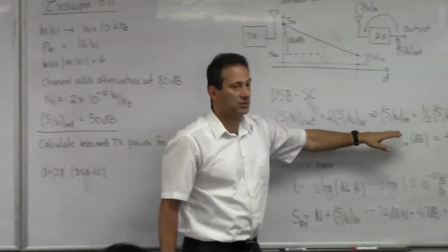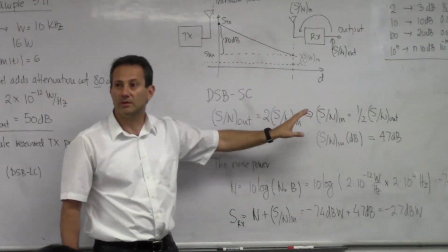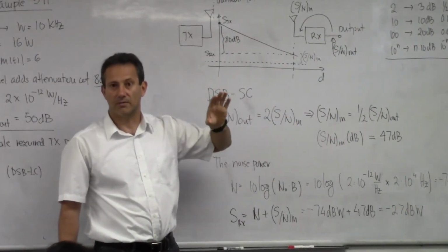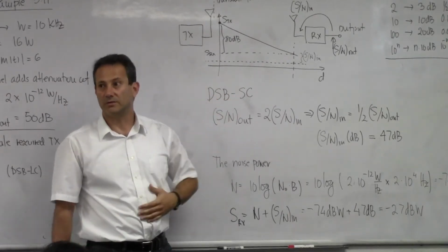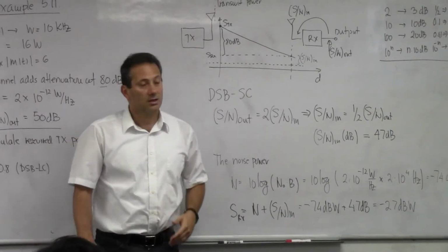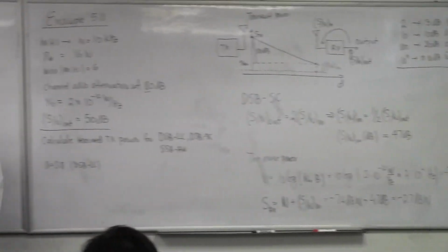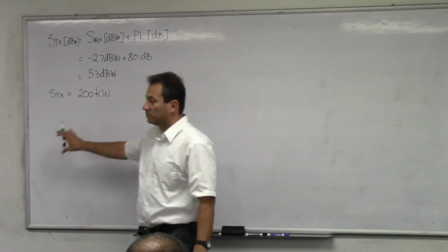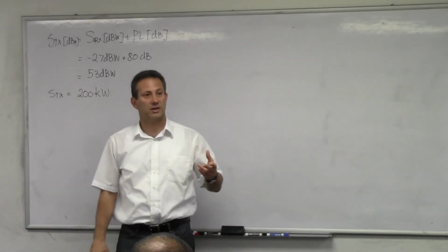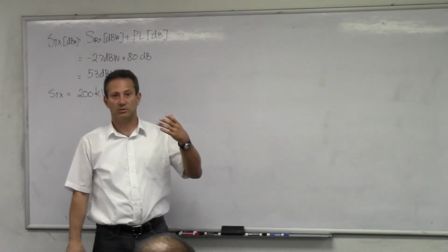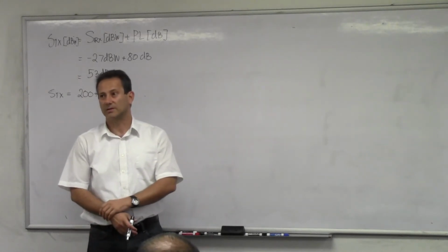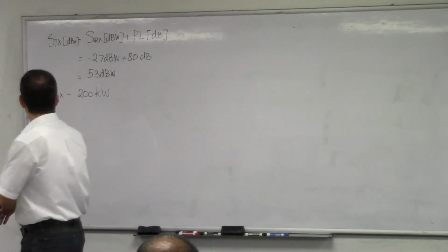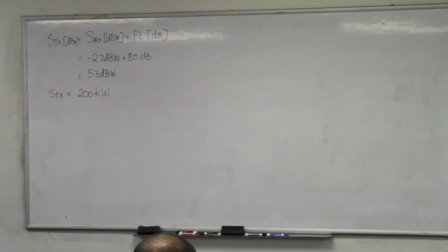Your signal to noise ratios are now going from 40, 50 dB to around 15 dB. So your digital television needs 15 dB to operate properly. That means that these powers are becoming much, much smaller. A typical digital TV broadcast station is limited to 15 kilowatts. But it's still kilowatts, thousands of watts. Right? So that's what we are transmitting.